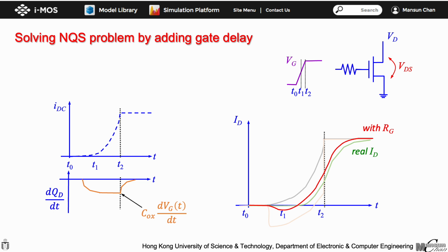However, it still produces a non-physical negative current after the VT, because this approach did not account for the pinch-off effect at the channel region near the drain. To summarize, the quasi-static formulation in Spice may break down at extremely fast switching in transient simulation. The question is, how serious is the problem? It turns out it may not be very serious.